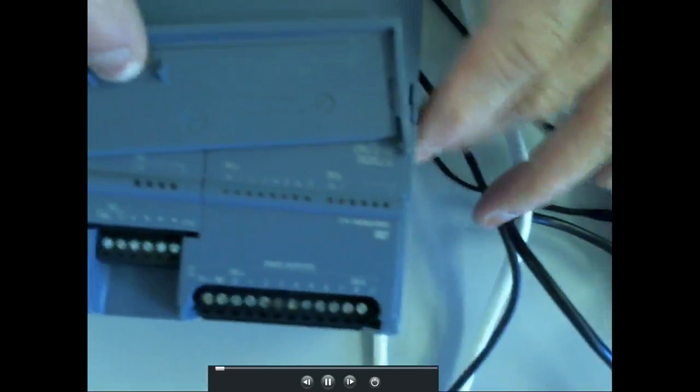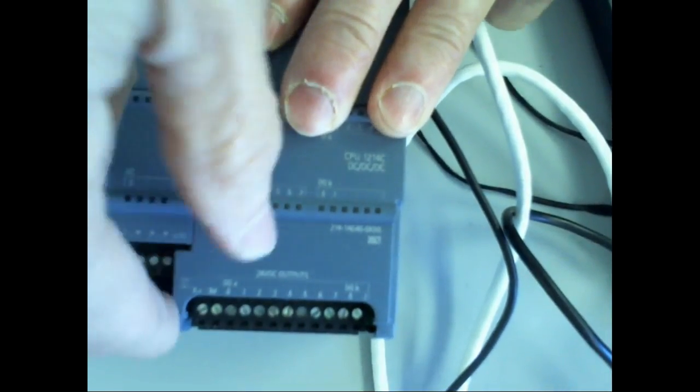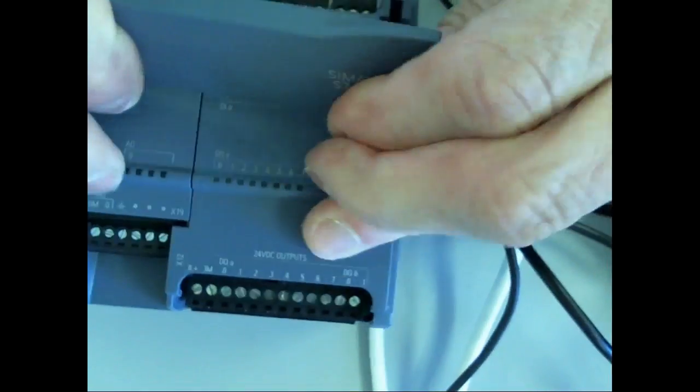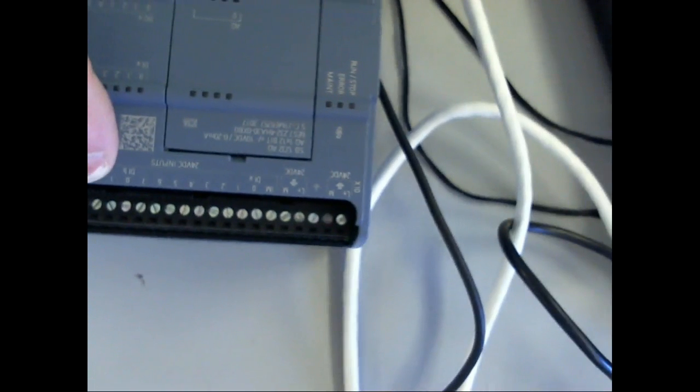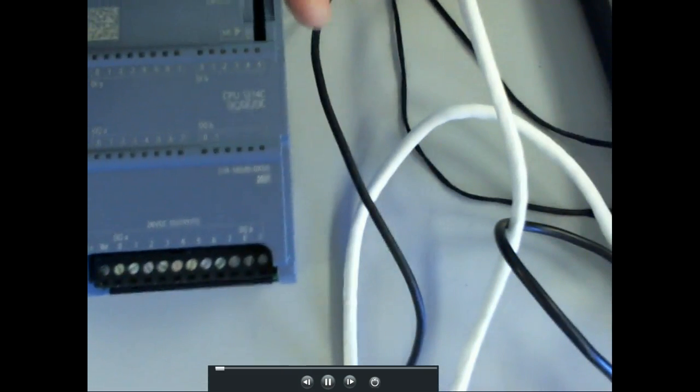computer. This is a fixed PLC right now. A fixed PLC means, got to remember which way I'm going. It's going to have so many inputs on it, and this is where I connect to the inputs right here. This is where I make physical connections to the input. And then it's got so many outputs. No, these are DC ins, I'm sorry. And these are DC outs. I got that backwards.